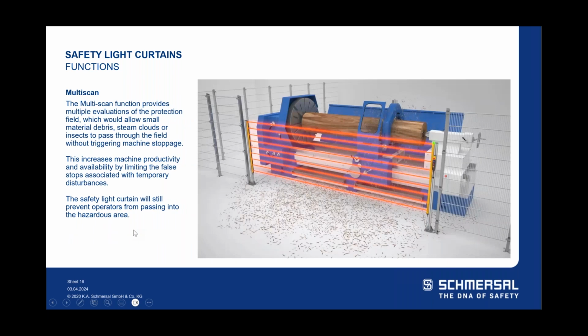Another neat application: sometimes you might think, oh, I'm not sure we can use light curtains here because, you know, wood chips are flying. I don't want nuisance trips, things of that nature. We have a multi-scan option where it provides multiple evaluations of the protective field. So it allows small material and debris. We have another video of steam going through it and it's not tripping it. And here an insect could pass through it, and not trip it just because it's constantly checking it and checking it and checking it.